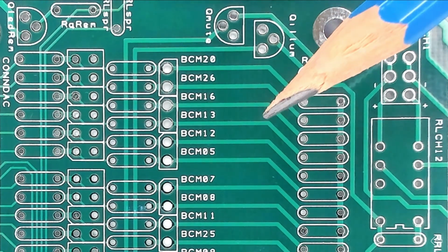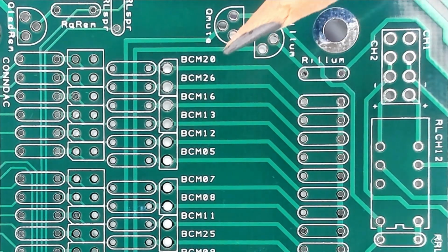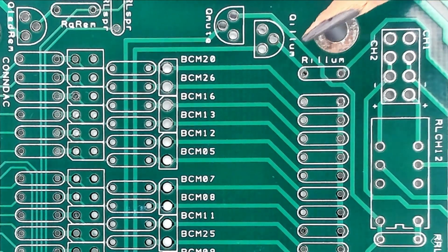We can locate all of the different components on the board wherever we think it's necessary and connect them with the traces. There's a few things we've got to keep in mind. Every board has multiple layers. The simplest of the boards, especially the one that we're going to create, has 2 layers. So we have a layer on top and a layer on the bottom. And if you look closely at all of these different traces, notice none of them cross. And that's important. You can't cross a trace with another trace on the same layer of the board.